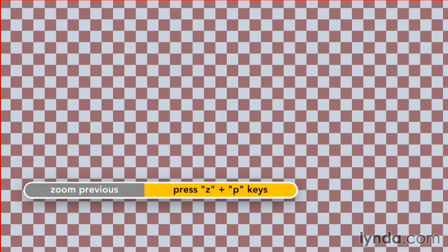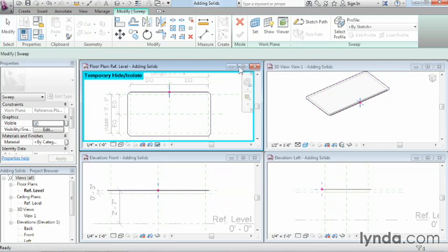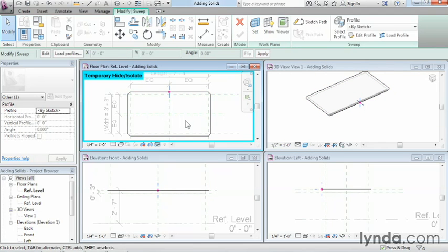Now, I'm going to change the offset back to 0, switch to the Line tool, and I'm going to zoom in at one of the corners, and I want to draw a little chamfered corner right there. Go to my Trim and Extend tool and clean that up. And I want to do that on all 4 corners. So I'm going to zoom back out, zoom previous, and repeat. And so I'll have a nice chamfered corner at all 4 edges. I'm going to click Finish Edit Mode. That completes the path. So you know that the path is complete because it changes color from magenta to black.